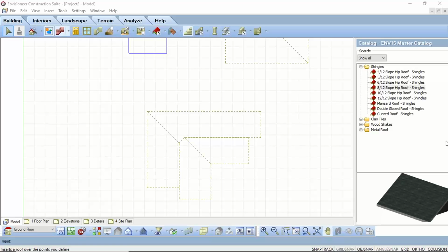We then looked at how you can connect your surfaces together using your Intersect Planes option. We talked about how you could go through and you can take those edges and you can manipulate them with the roof edge type editor to create your fascias, your gables, your hip, and your ridges. And we also looked at how to take a surface and you can add a surface in as a roof, as a ceiling, or as a floor.